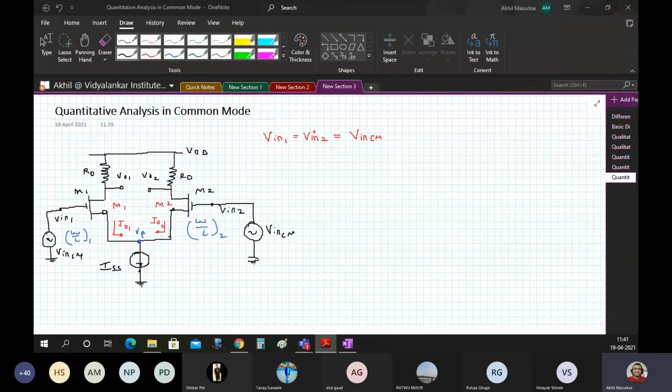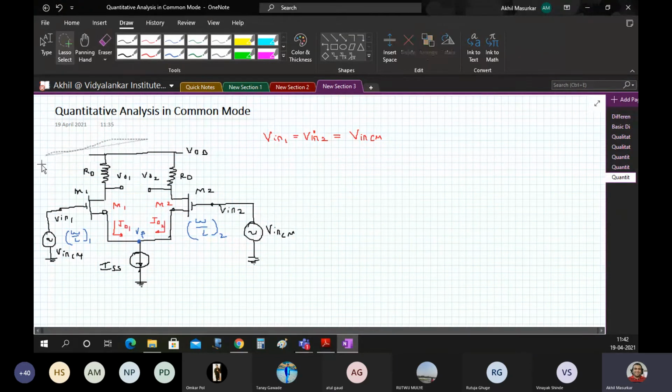And that is the reason why we have to find out how much part is actually going to disturb the circuit. Therefore, we first assume that the circuit is symmetric, but the current source does not have an infinite impedance. So let me assume that RD is the same on both the sides, but the current source that I am using is not going to have infinite resistance. An ideal current source must have infinite impedance, but we have to deal with the practical situation, and that is why we can claim that I have maintained symmetry, but I cannot claim that I have made an ideal current source. And since that ideal current source is not possible, what actually happens is somewhat like this. I am just taking this circuit.